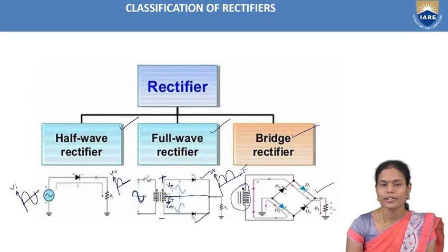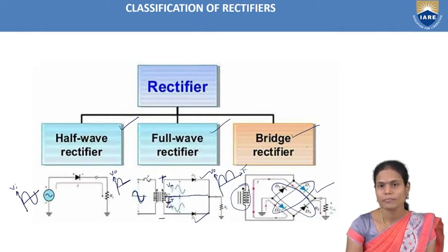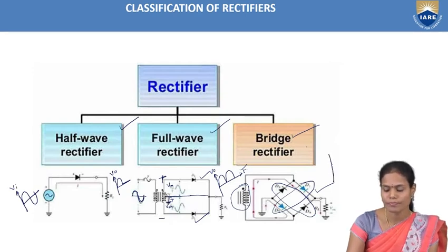That is, two diodes are going to conduct at a time here. For one half cycle two diodes will conduct, and for the other half cycle two more diodes will conduct, and the two particular diodes will operate in series, so the function of both rectifiers is similar. But construction wise, there is a difference between both rectifiers. In analysis wise as well as in the output voltage, there is no difference between both rectifiers.